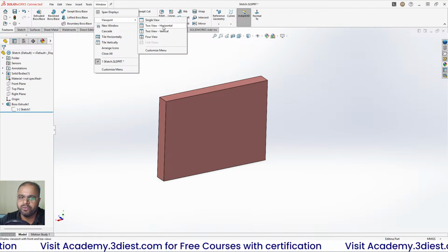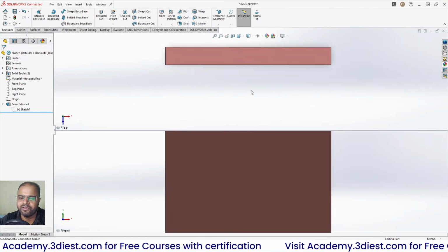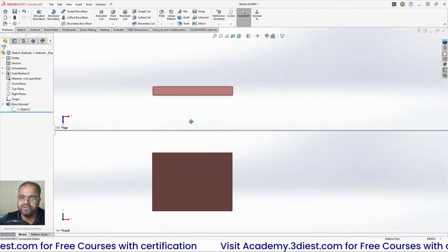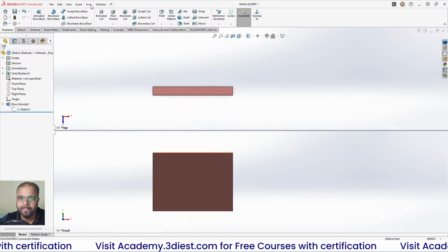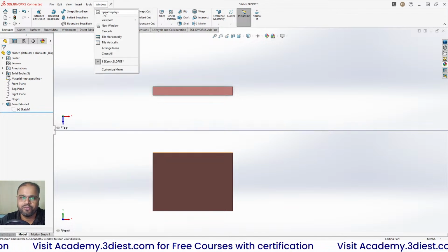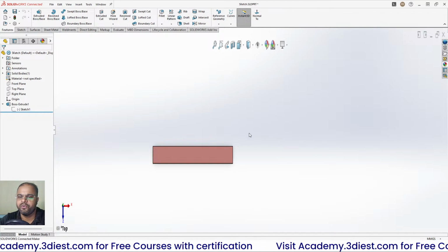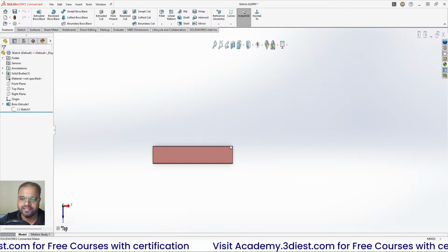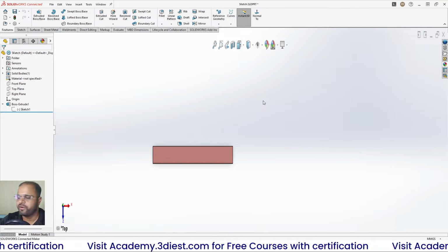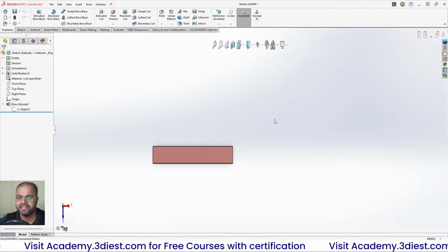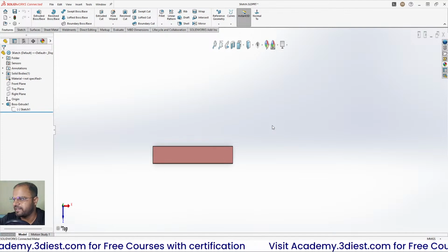If you click on the two view horizontal viewport, all things just got divided into two different viewports, divided horizontally, right? So these are the small things that you can explore, like how you can change and arrange viewports inside SolidWorks. This will take time, you don't have to worry about that. When you are just getting started, just stick with the basic settings, I will say.